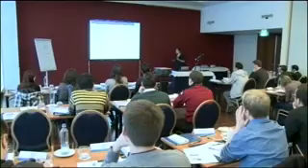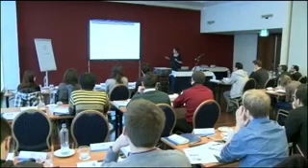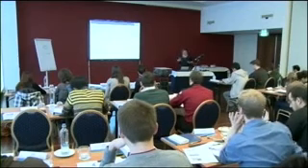Right? Now we're just going to take 2 minutes on this exercise. It should be quite easy for you. But I just want you to try and do a very quick calculation: if the water-cement ratio is 0.5, and the density of cement is 3 grams per centimeter cubed, and the density of water is 1 gram per centimeter cubed, try and calculate very quickly what the volume of solid is in that total assemblage of cement plus water. Okay? So you've got 2 minutes to work that out. And it doesn't have to be very accurate. We just want a rough idea.